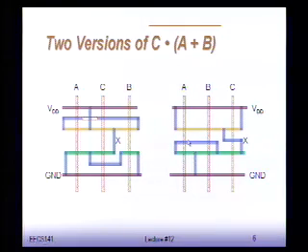So let's look at what happens if we instead order them differently and we put A, B, and C. First of all, because the first two transistors are A and B, I can choose to assign this node either as their common drain or their common source, right? A and B are completely in parallel, so they have both the drain and the source in common. However, if I decide this to be the drain of A and B, then this also needs to be the source of C, okay? And again, we end up in a situation where we can get three fingers.